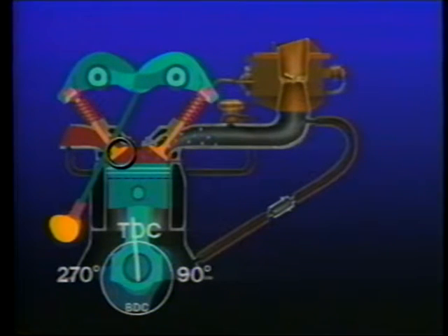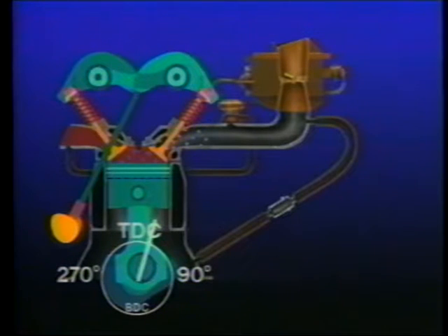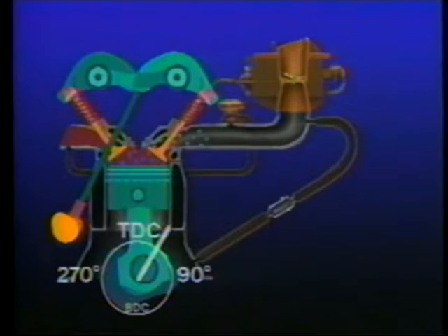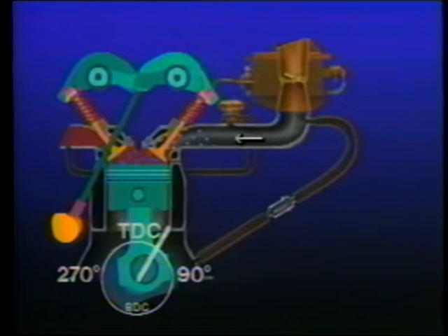The exhaust valve will remain open a small amount of time after the piston reaches top dead center at the end of the exhaust stroke. Even though the piston starts moving downward on the intake stroke, exhaust will continue to flow out of the cylinder due to its momentum. The intake valve, however, is also starting to open at this time. The fresh air-fuel charge will enter the cylinder due to the momentum of the air-fuel mixture in the intake manifold.